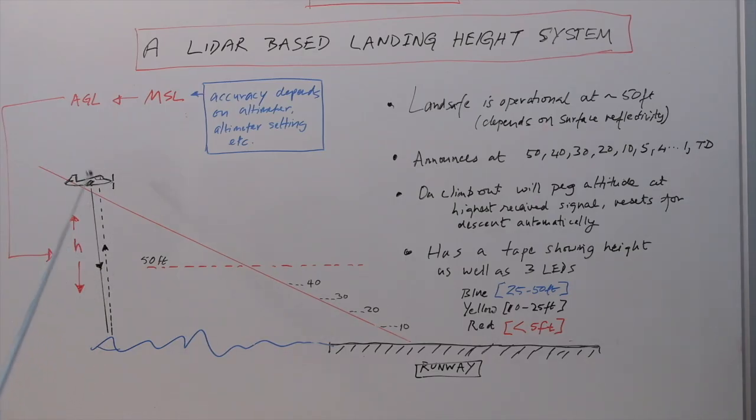Although when we have an MSL altitude, we determine that using barometric measurements typically, or using GPS, where it's corrected based on the Wide Area Augmentation System called WAAS, which allows you to locally correct for imperfections in the datum, that is the plane that is used to calculate what is considered to be ground level, which is 0 feet.